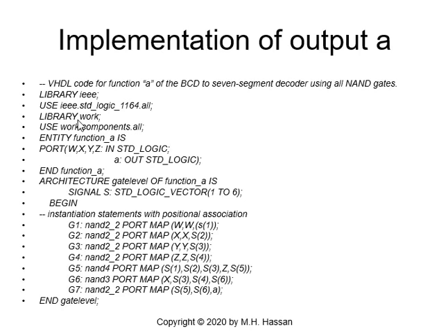This is very important. Library work and use those two statements, because the package is saved in the library work, and this work is on your compiler inside your computer only. So if you use a different computer, you have to repeat. You have to compile the package program again.